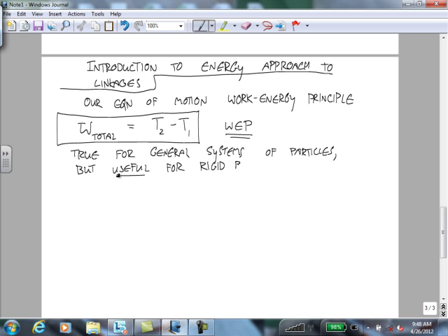Okay, so work energy principle, in physics, you dealt with that, right? Work energy principle is the kind of more general statement of what law? Like, you're more used to probably dealing with it as, yeah, exactly. This is the general equation that conservation of mechanical energy comes from. But this one, we have a way to apply external loads. Conservation of mechanical energy is just a totally self-contained thing. Okay, so this is an important distinction.